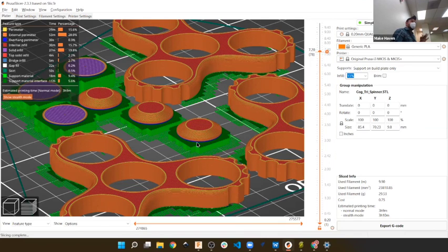Oh, it depends a lot. Sometimes it's super easy and sometimes it's really hard. For these six things that I actually did have supports and broke them apart on, I think three of them, and it's pretty random, three of them at random just kind of half fell off. And then there was one that I needed to stab with a putty knife to get it to separate. In a perfect world, it would be just a light little snap and it pops off, but it's almost never that nice. And then it's different for different printing processes. So you just got to sort of get it.